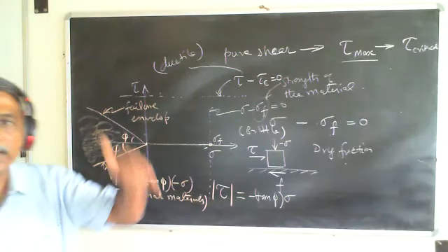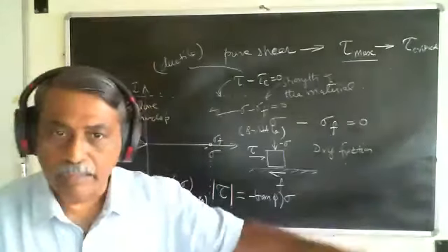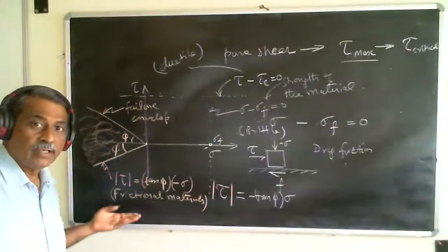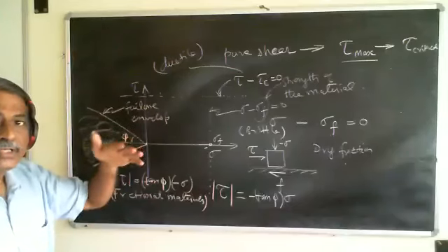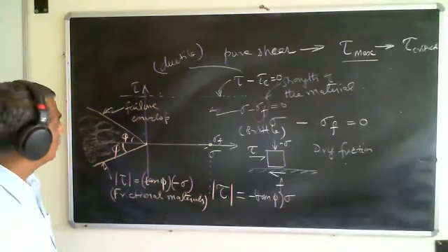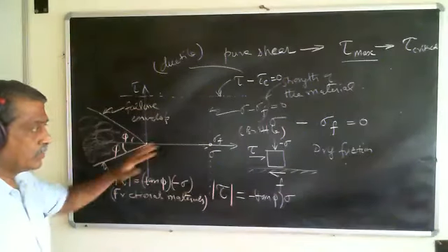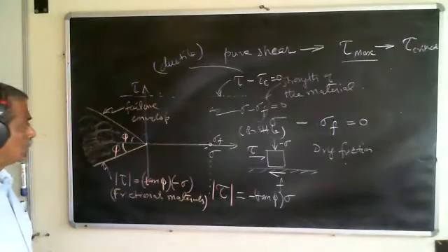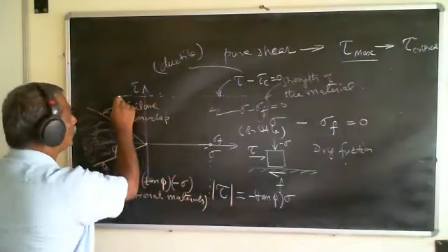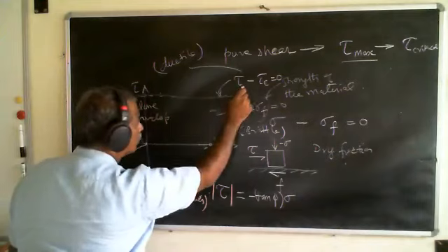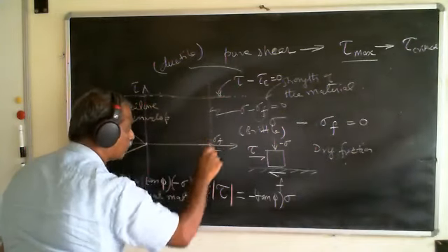Often you would have seen sand piles with an angle of repose. That angle of repose is connected to the friction that it offers, beyond which it starts to slide. So far, so good. Any questions on this understanding? Remember, we are drawing the envelope. This is one envelope that we drew, which is tau equal to tau c. This is another envelope that we drew.